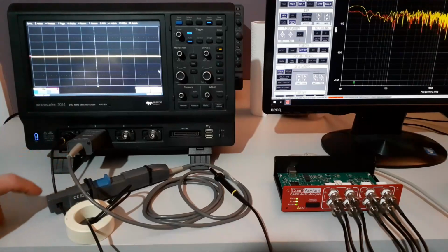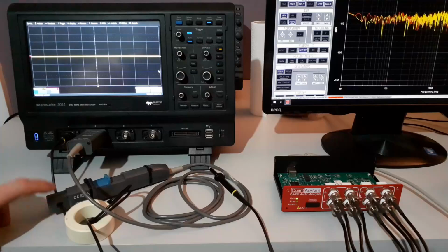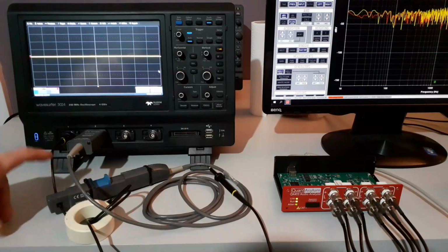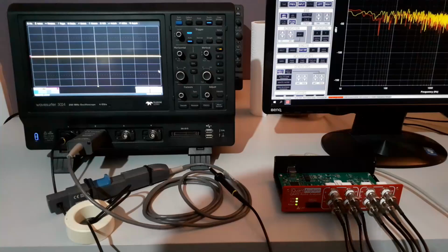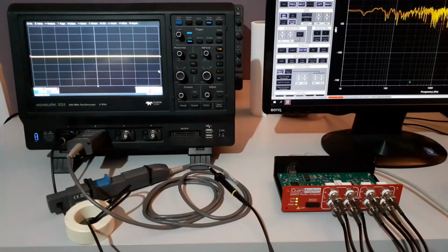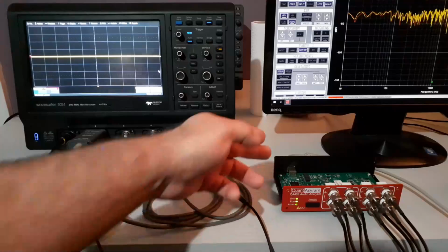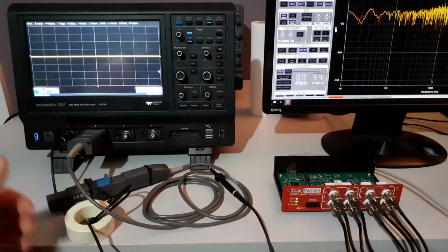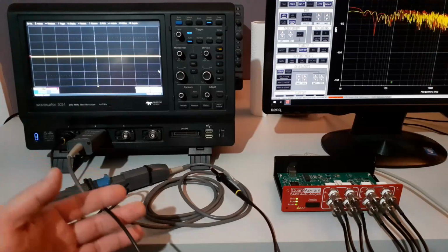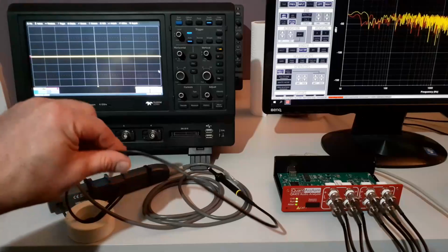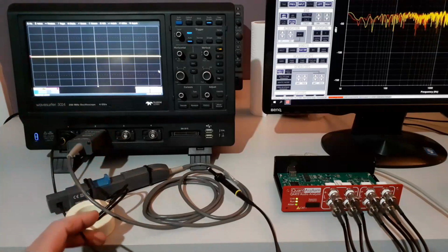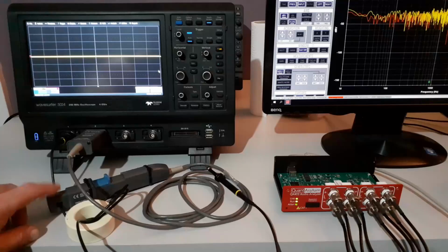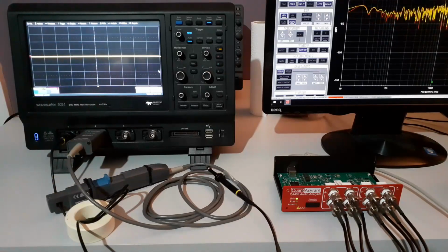And also I'm looking at common mode current with my LeCroy AP015 current probe, because there is an unwanted ground loop coming in here, and a little bit of DC current is flowing on the oscilloscope's probe ground. I also want to check that DC current loop.